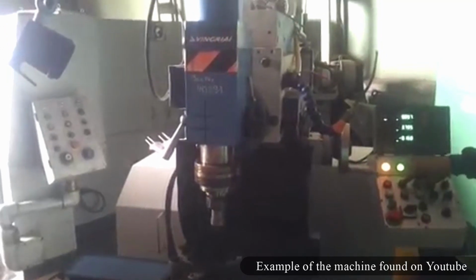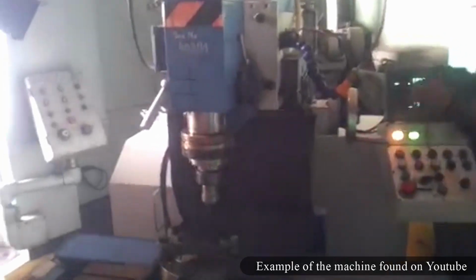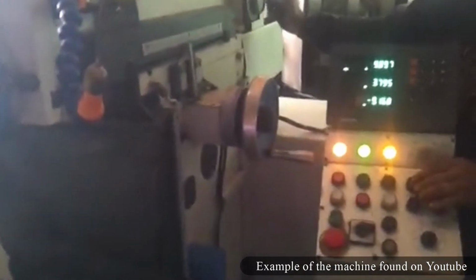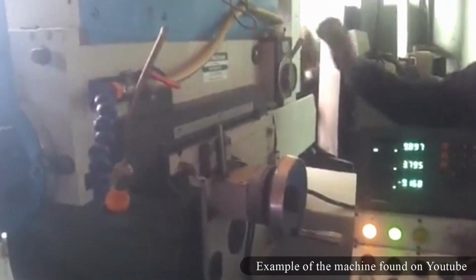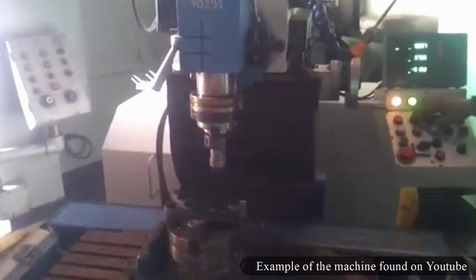A little backstory. About a year ago, I helped someone who had bought an old Soviet-era milling machine that had its control box missing. The brains of the device had either been stolen or sold separately before he bought it. The X, Y and Z axles of the machine were controlled by stepper motors, and we needed to generate pulses up to 5000 pulses per second to drive them, which means a pulse after every 200 microseconds. Since the machinery is heavy, we also couldn't just start at 5000 pulses per second. We needed to accelerate and decelerate to alleviate the forces caused by inertia.